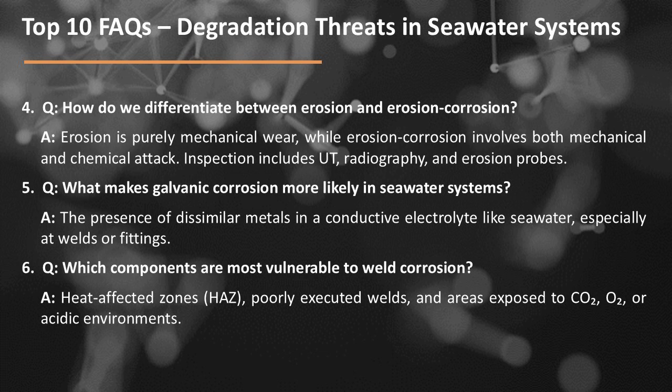Question number 5. What makes galvanic corrosion more likely in seawater systems? Answer: the presence of dissimilar metals in a conductive electrolyte like seawater, especially at welds or fittings.